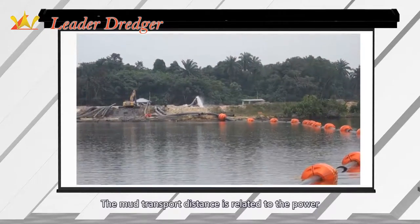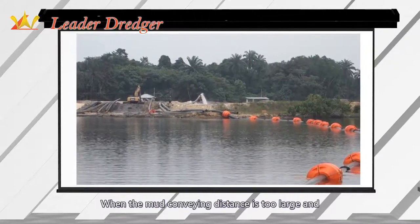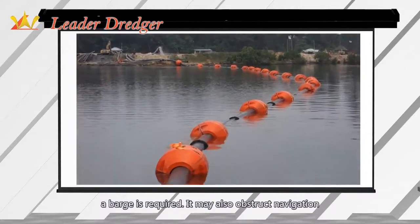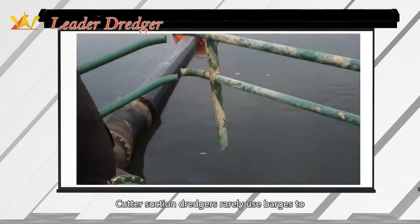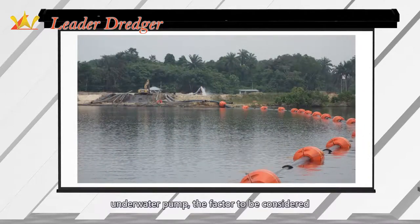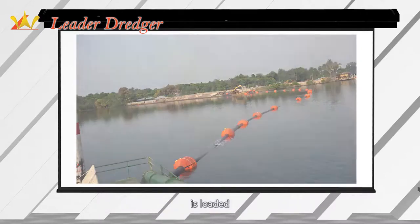The mud transport distance is related to the power of the mud pump and whether a barge is needed to transport mud. When the mud conveying distance is too large and the use of hydraulic mud pipes is not economical, a barge is required. It may also obstruct navigation, so mud pipes need not be used. Cutter suction dredgers rarely use barges to transport mud. If the cutter suction dredger is equipped with an underwater pump, the factor to be considered when selecting the power of the underwater pump is that only this pump is working when the barge is loaded.